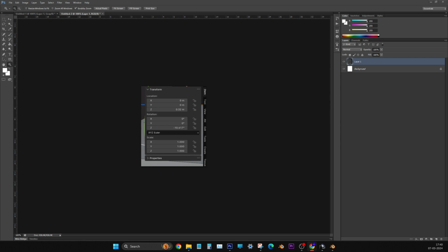This is called sync. So you know which one you are selecting in the 3D viewport. Select that also and see. Yeah, all the faces. Top, bottom, and then back, and then sides. They are sides, small, small triangles. Now you just imagine one texture you are pasting on it. This UV you are seeing, on the left side panel.